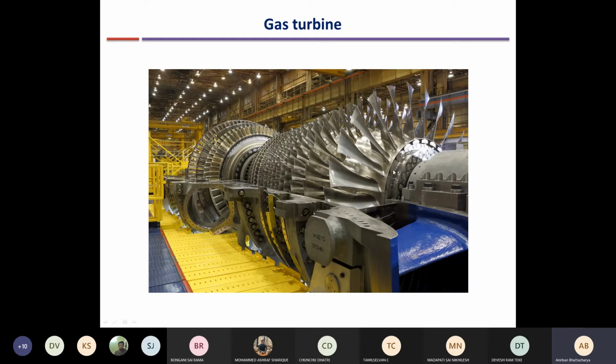Okay. So the air, say it's an industrial gas turbine, at the inlet is at normal atmospheric pressure and temperature. After passing through all these stages, the pressure may be increased by around 20-25 times. So instead of 1 atmospheric pressure, now the pressure can be equal to 25 atmospheric pressure. Okay. So with this high pressure, the temperature will also increase, obviously.